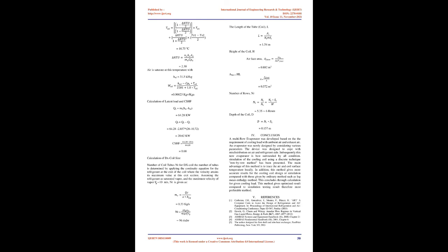Plate or ripple fins are used to enhance the heat transfer area. Thus the primary surface area, the outside area of bare copper tubes, is enhanced greatly by adding a secondary area of fins. The total area including fins is called the outside surface area. The cross-section, L times H, through which the air flows, is called the face area or the fin area. Thus L is fin length and H is fin height. Fins are arranged perpendicular to the tubes, where the fin spacing varies between 8 and 16 fins per inch of tube.